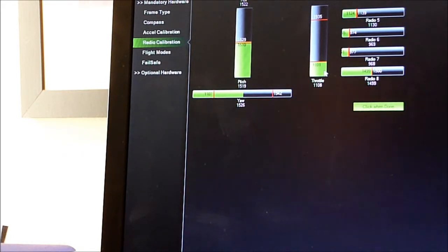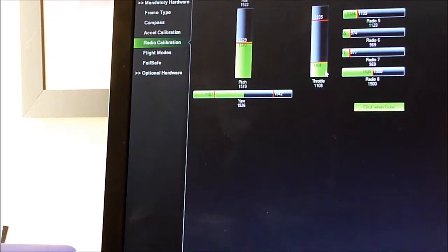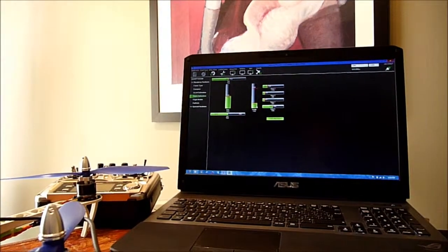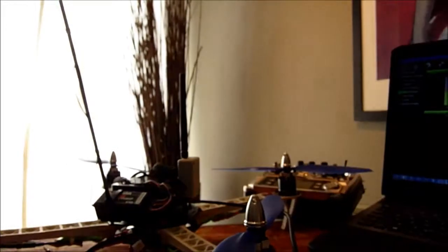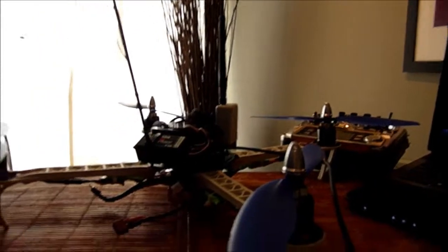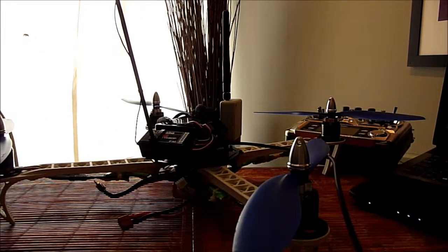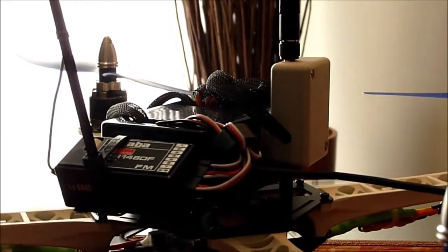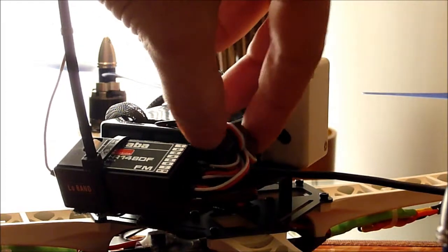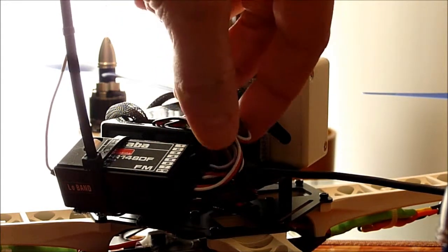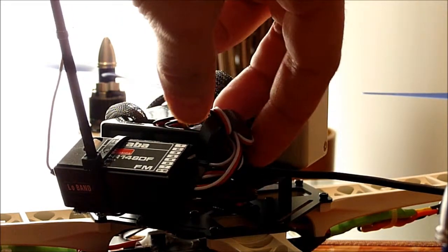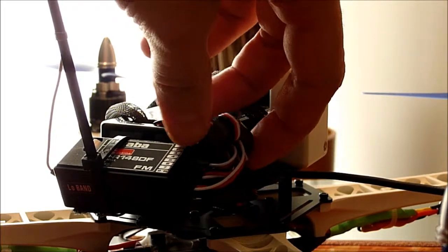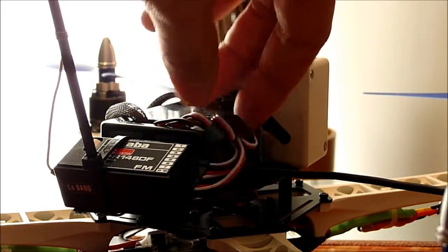That was another issue. Now, a lot of that was eliminated as soon as I added all the ferrite cores. They do come in different sizes, different shapes, and things like that, so they are available. Here's one extremely large one here, so I can put all the wires through. But they do help a lot. These do remove a lot of the interference, and it does make everything a lot more stable.